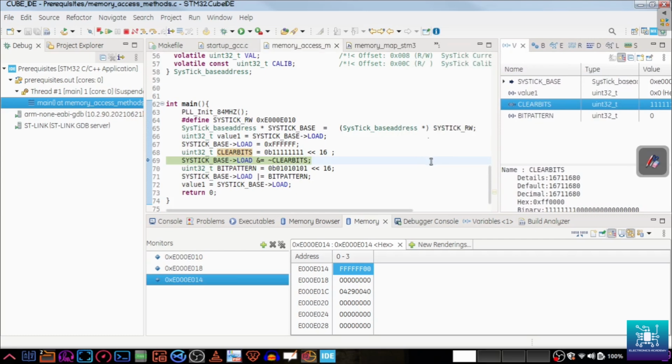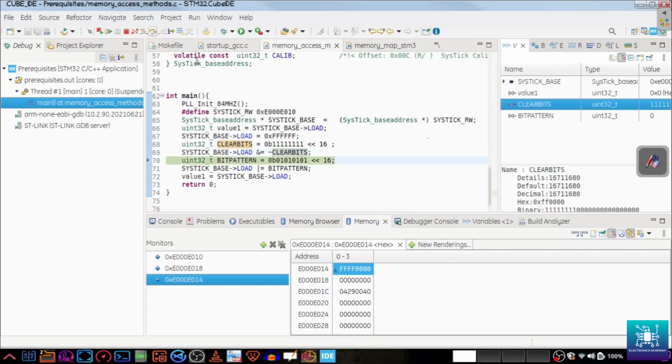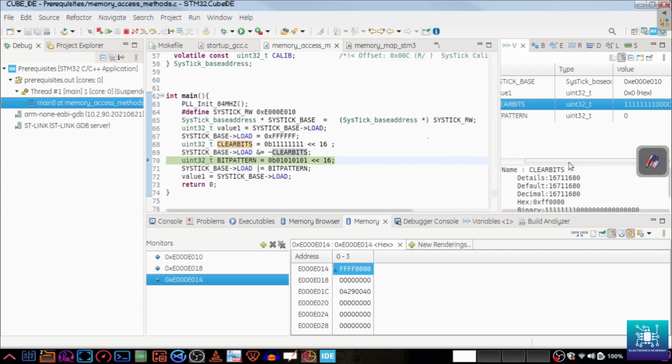All right. So now we have to clear that. So keep an eye here. That is those top 8 bits we have to clear before we write into them. So one more step, and what we see here is, if you check the bit pattern here, one F has reduced here. It was all F's, now one F has reduced. That is, the top bits have been cleared up.